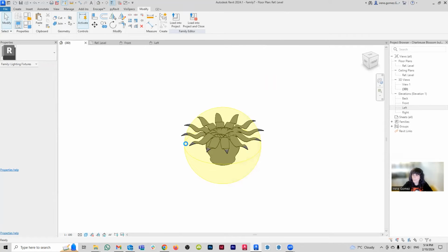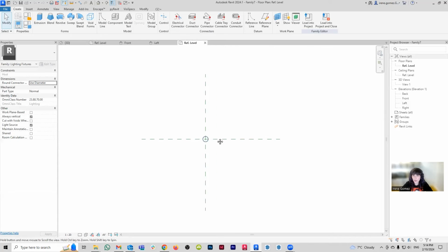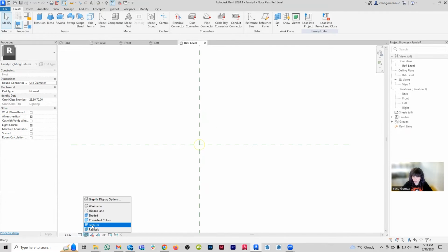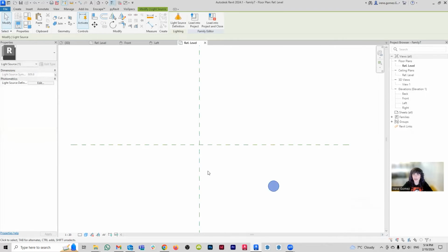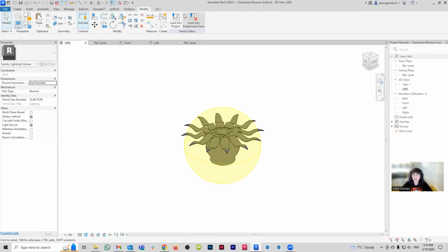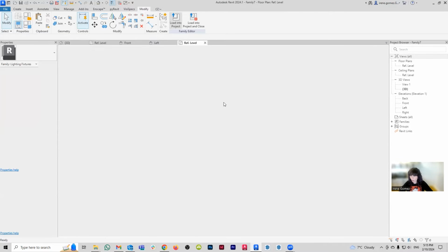So I'm going to go here. We have another lighting fixture already existing. Do not worry about it. We will tackle this guy in a minute. So for now, I'm just going to move it out of the way. And now I'm going to load in, I'm going to nest in my bulbs. So I am going to go here and I'm going to load this family into my new family.